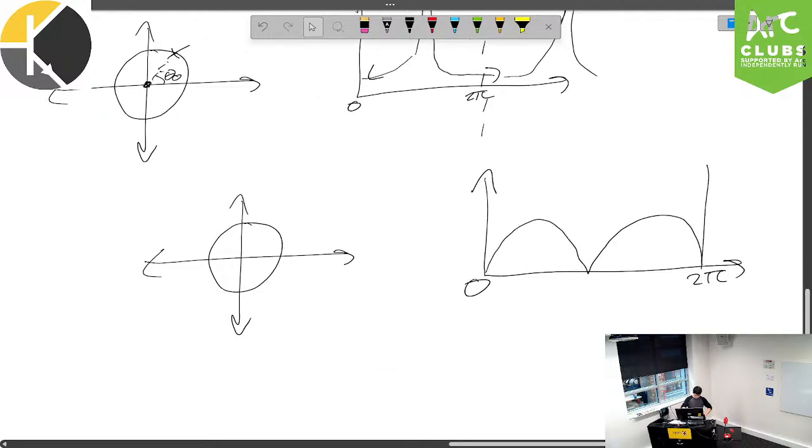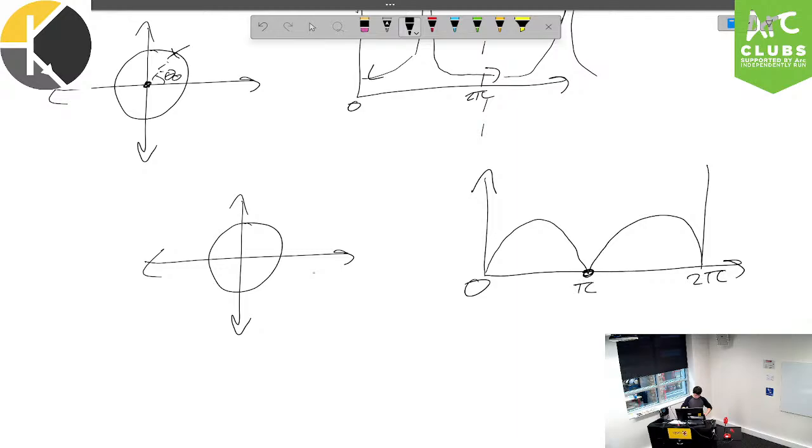So in this instance, we want zeros at both 0 and pi. So we go ahead, we put zeros there. But also, we want to have a raising directly in between, okay? And to really implement this to our best ability, there are a couple things we could do. We could just put our poles directly in the middle, but if we want to emphasize it a little bit more, we can raise them a bit.